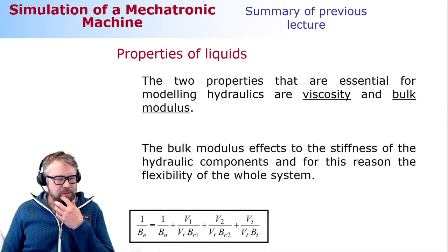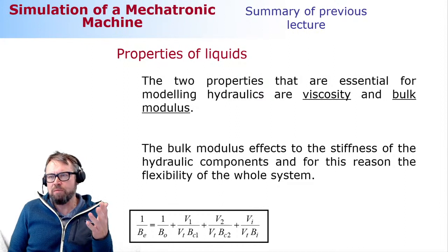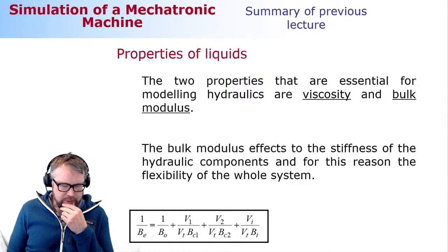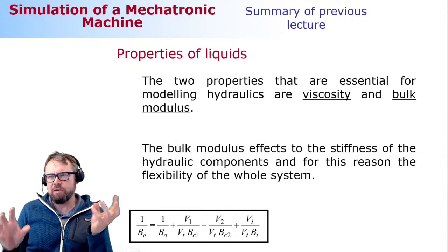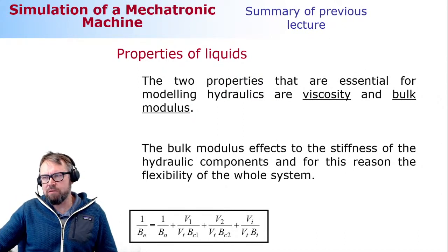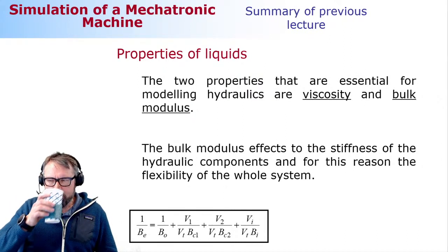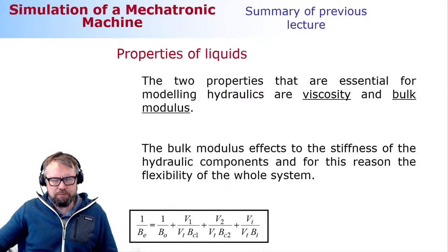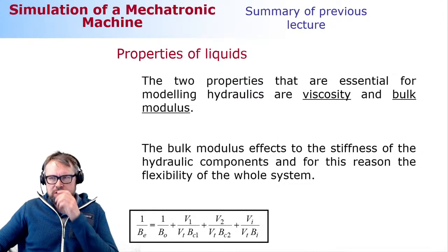It's common that you have malfunctions and problems in hydraulics. A typical problem in mobile machinery, where hydraulics is heavily used, is the hose connection, which is the rubber connection between the components. These hoses tend to break, and that causes the oil to go out of your system.